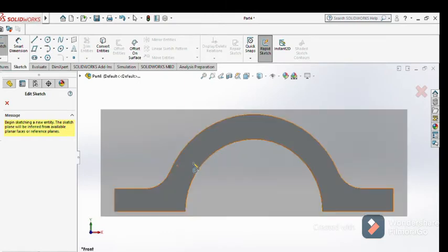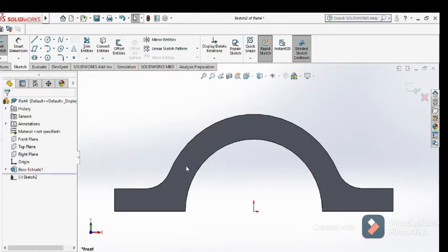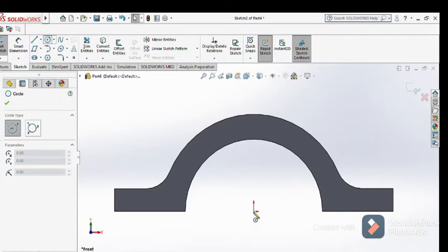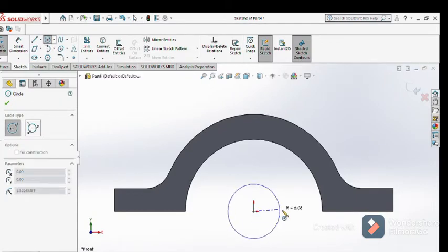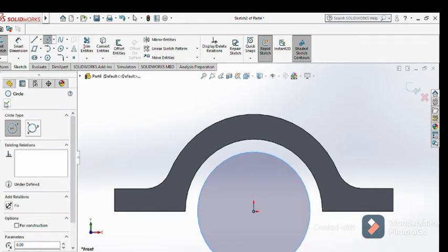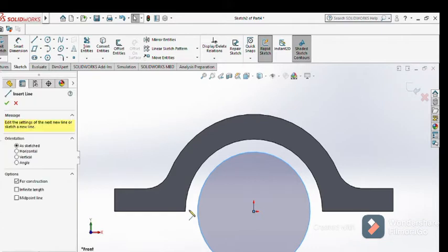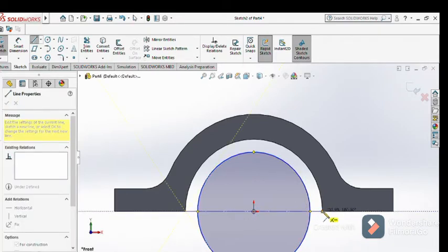So if I click here, I choose a sketch. Since I chose a sketch where I wanna show my diagram, I click in my circle again, and then I draw my circle. Done. Then remember guys that I need to put in my center line so that I can cut off the unnecessary things that I don't want.